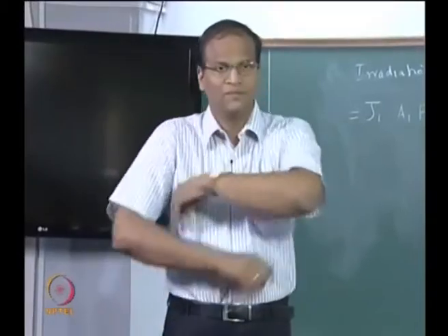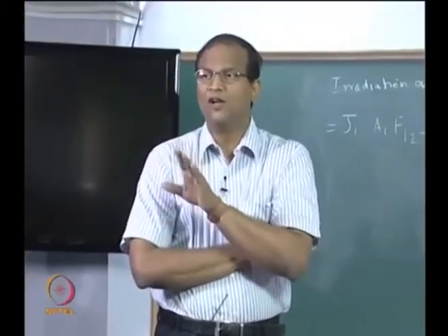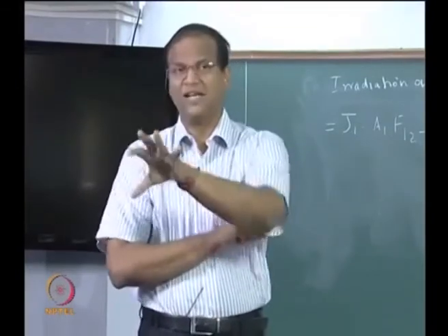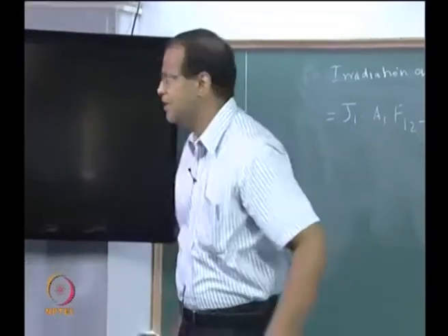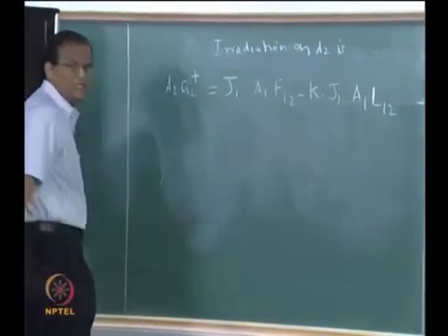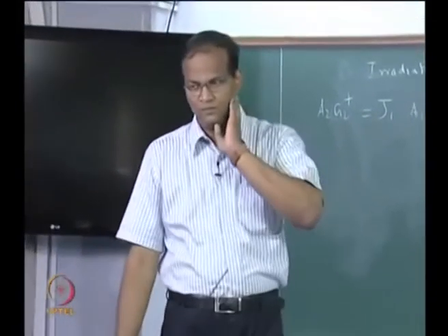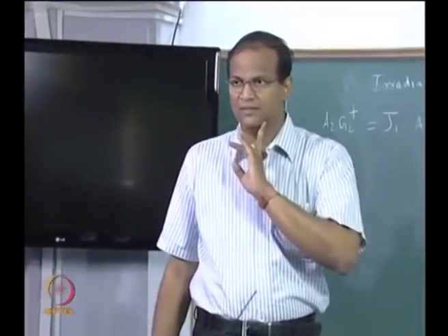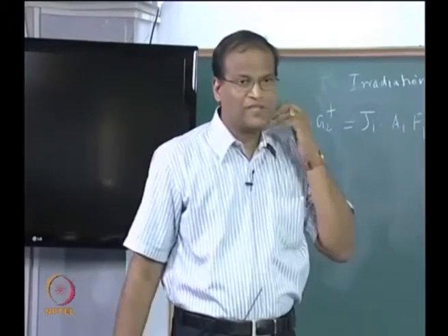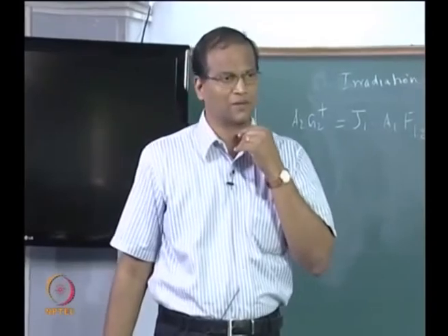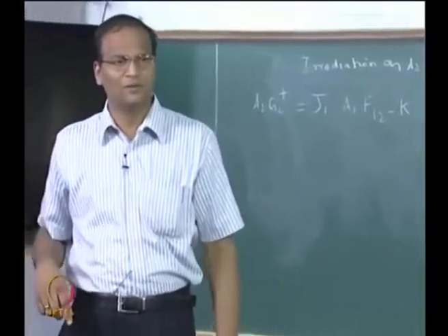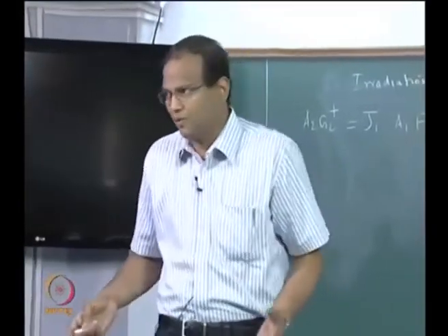Now, this is equal to irradiation falling on the area 2 basically from the wall element, we have not considered the irradiation coming because of the gas radiation, okay. So, this will be equal to A2 G2 star, correct, because everything is in watts, right side is also in watts. J1 is watts per meter square, F is dimensionless, A is meter square, okay. But now I do not like left side I have A2, right side I have A1, I do not like this, so what can I do? Can I do something? Yeah, I can use the reciprocal rule, okay.